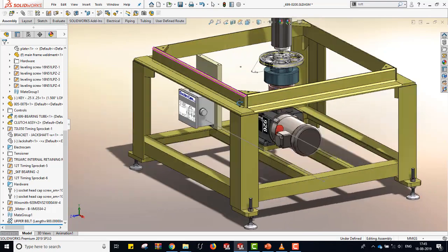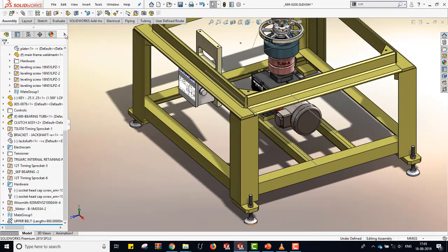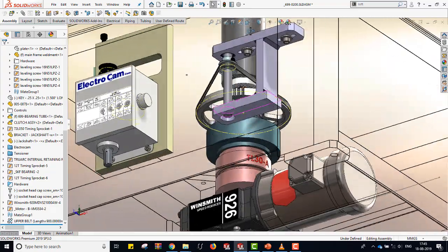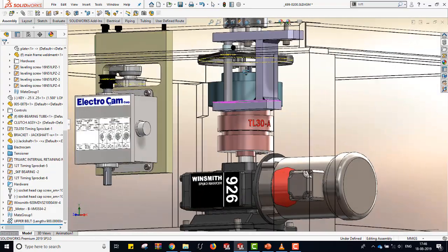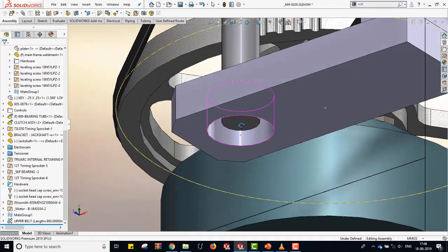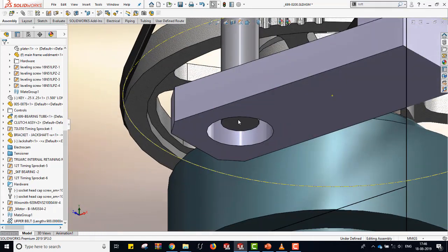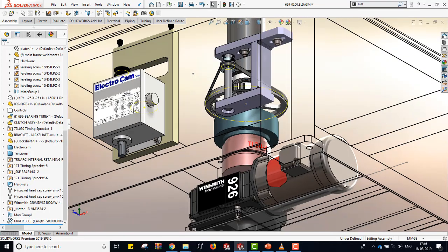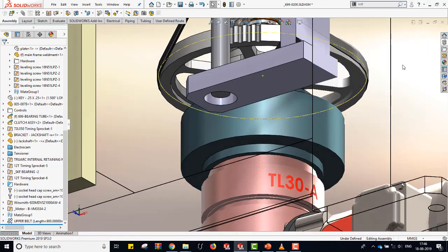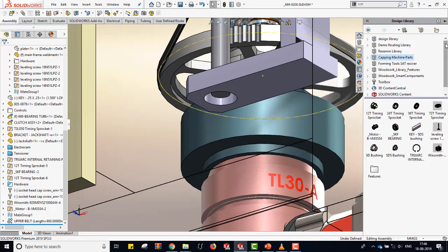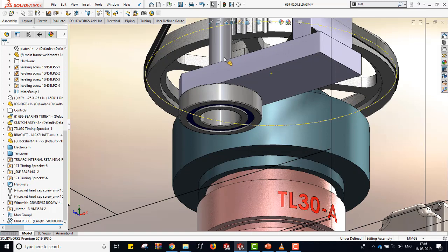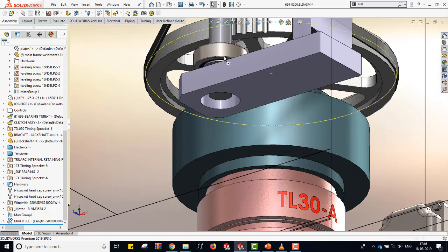Not only that, let's move a bit further. Let me change to its belt drive condition. As we all know, our system requires belt drives and certain other drives. Not only that, in a belt drive, I need to put a bearing or a circlip over here. Similarly, I can make my toolbox components like bearings and circlips smart components. So in this particular condition I need to put a bearing over here. Let me quickly drag and drop one bearing over here.